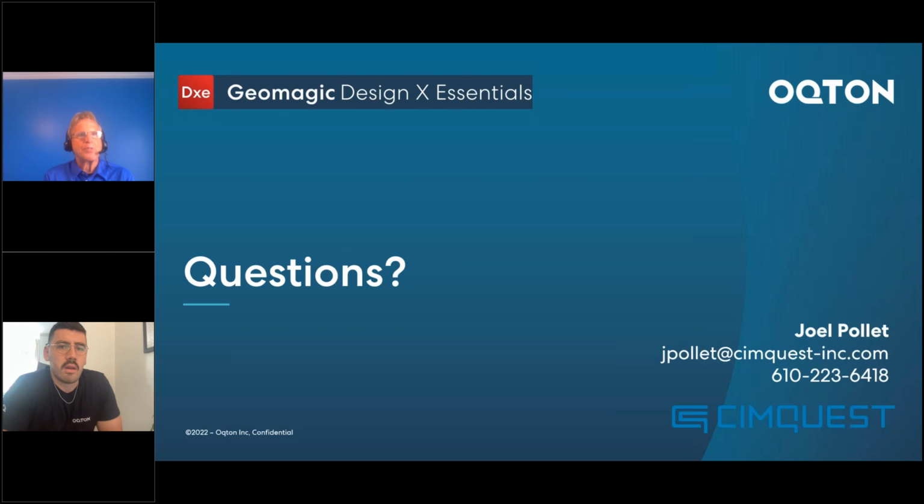So to prep a model for 3D printing is actually much simpler than to do what we did. 3D printers generally only care about having a fully enclosed volumetric shape. So you could use Geomagic Essentials to import a scan. Then you can use tools in Geomagic Essentials to fill any holes and repair any deformities in the model. And then you can just save back out that polygonal file as an STL. You could just export it back out.